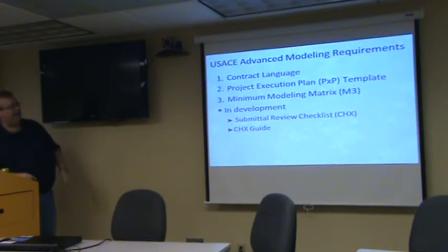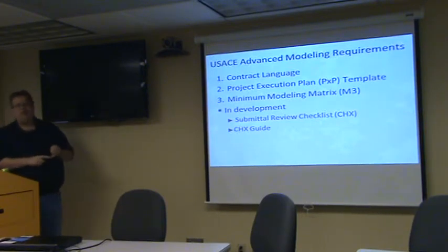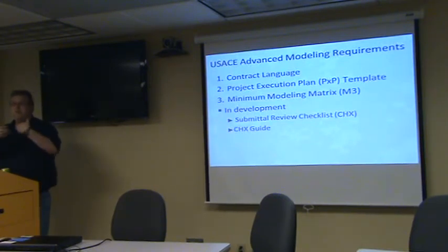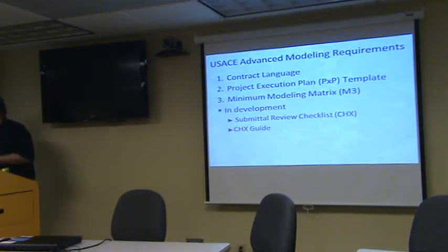In development right now, there's a submittal review checklist to help you and the Corps. So when you submit something to the Corps, you have a checklist showing you've met all the things you have to submit. Have you submitted an editable authoring model? Have you submitted a non-editable viewable model? Have you submitted CAD compliant DWG files? Have you submitted a visualization? So you go through a checklist. And the guide is to help you and the Corps who's delivering it make sure you're doing it right.